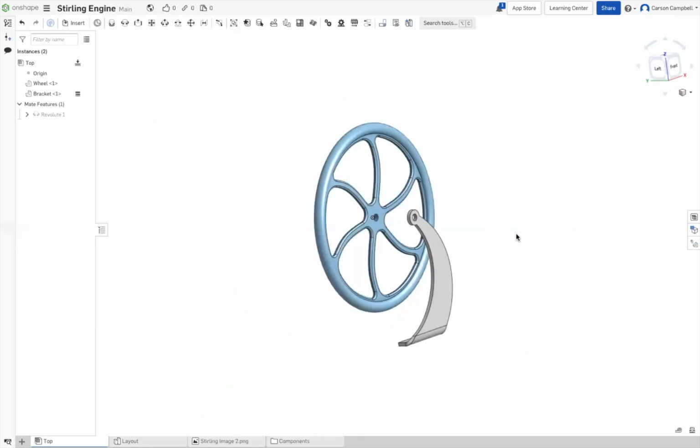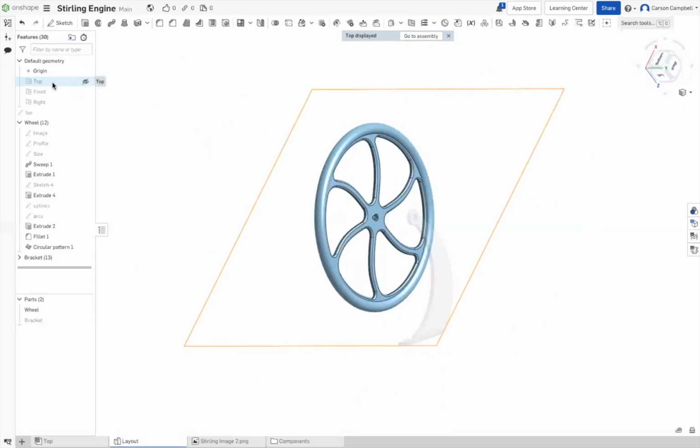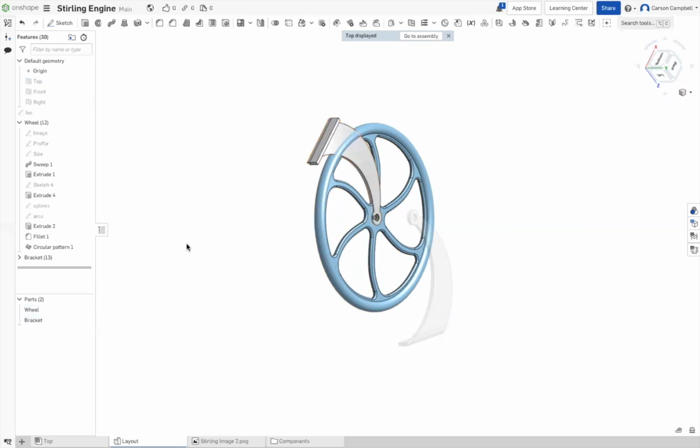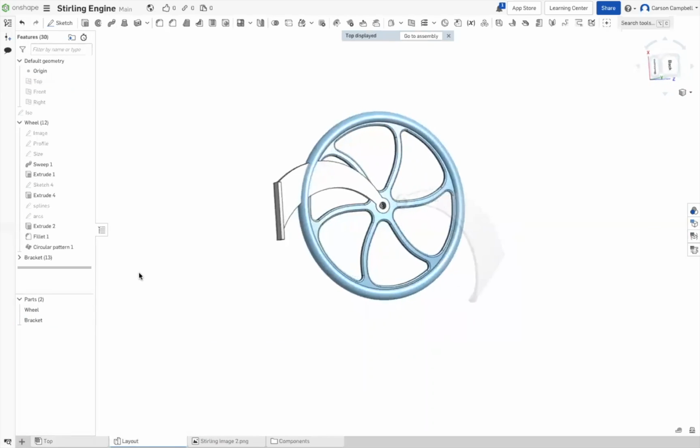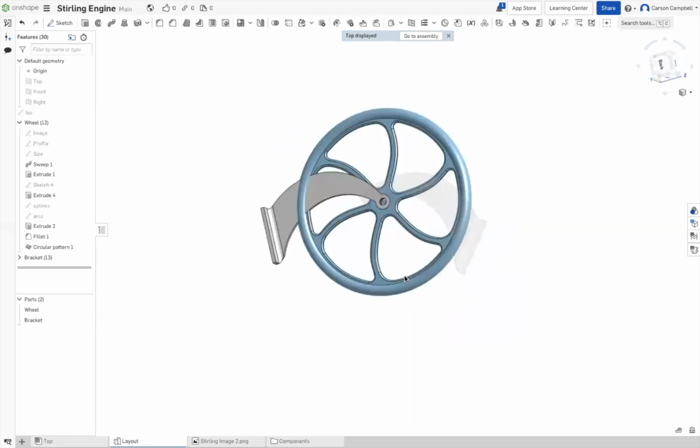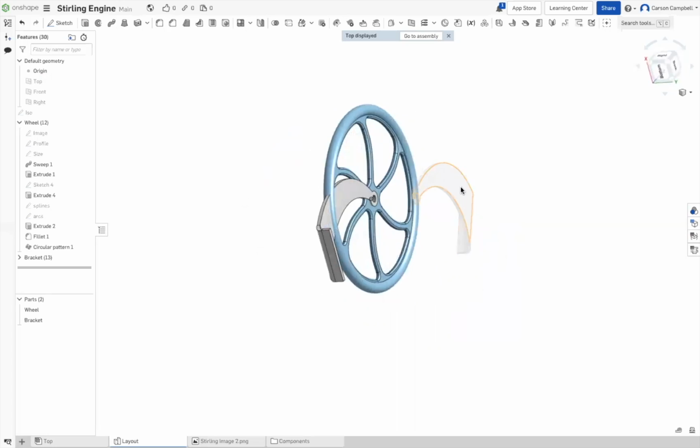Double click the word wheel in your layout. So now what we're doing is we're back into the layout. Highlight bracket below down in parts and show it. Updated from what was in the assembly, or what's up? No. So one of these views is how you're building the part. The other view is the assembly. Okay. So we got some work to do here, because what I want is I want the assembly to kind of match the part studio.